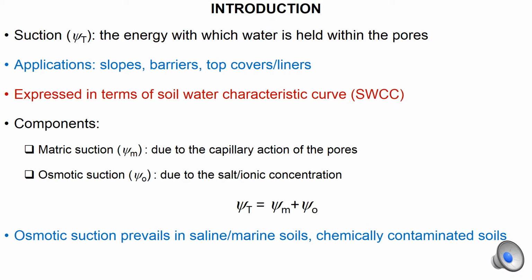technique. To start with, suction is the energy with which water is held within the pores. It finds its applications in slopes, barriers of waste containment facility, top covers or liners of landfills, dams, and embankments. It can be expressed in terms of soil water characteristic curve or in general water retention curve, which is a function of suction and moisture content.